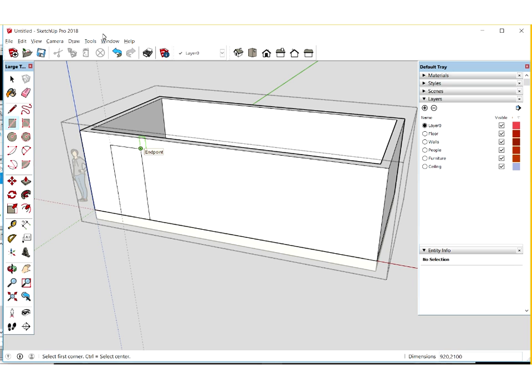Right, next step, our main modeling tool, of course, is our push-pull tool. So if we click on the push-pull tool, I always think about where I'm going to start this. I don't start it up in the top corner there. I'll run out of push-pull space on the right angle to push this through. So I'm going to start towards the left side here. That'll make sense as I do this. So I'm sort of dragging back into that wall.